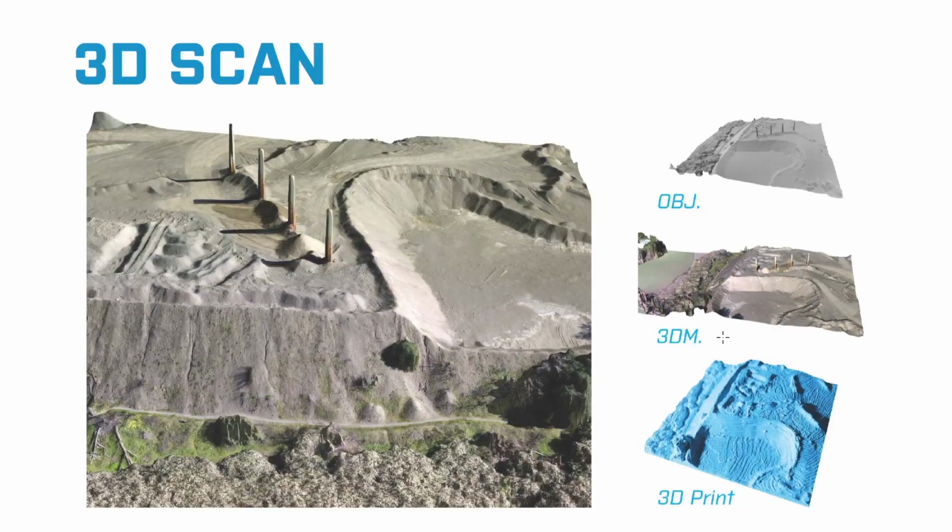So here we've got the 3D model, which is using that photogrammetry. It's able to create a 3D representation of the site that's actually very accurate. If it's bare earth, great. If there's vegetation, it actually maps the vegetation as a solid, which is the limitation of photogrammetry. So this is my project site that I worked on, and it is a gravel mine, so it's a perfect case for the use of this drone scanning.